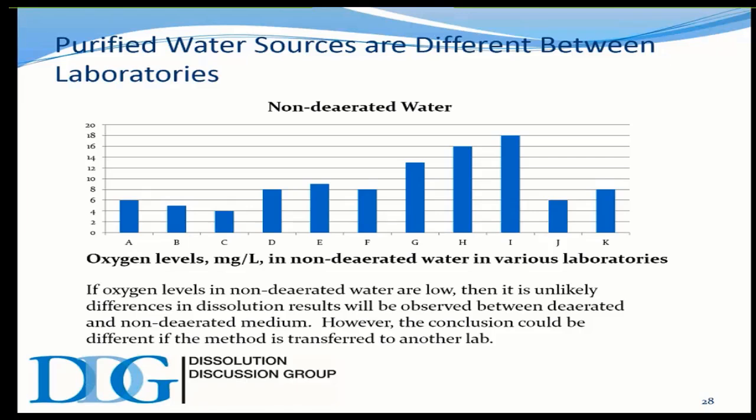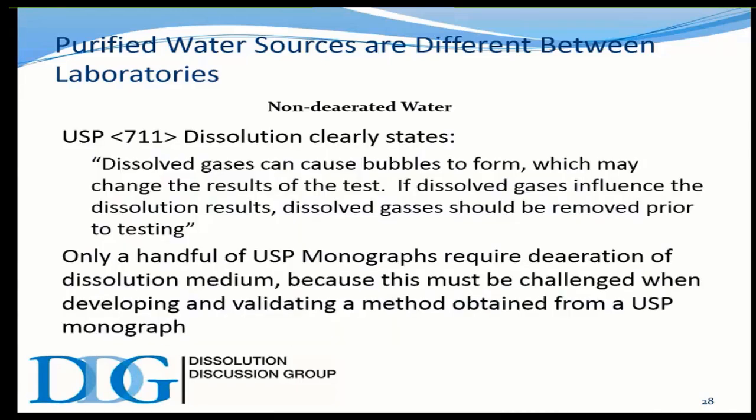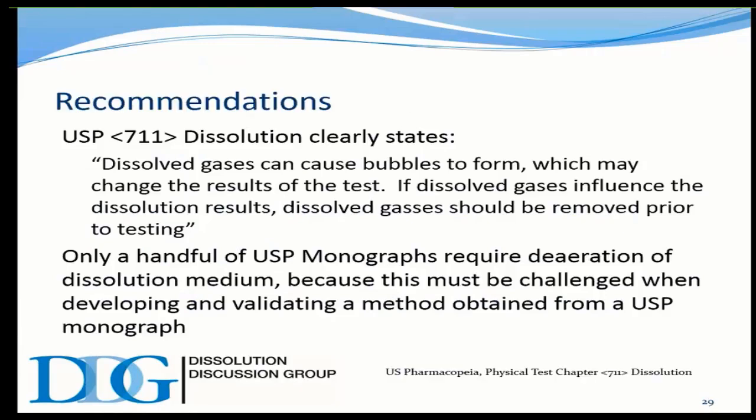Anyway, the key thing is to evaluate water on a saturated basis, and then once you've deaerated it sufficiently, down below generally 5 parts per million or so, that should be very minimal impact. So for anybody wanting to monitor it, again, I'm going to strongly suggest a dissolved oxygen type of measurement. And again, this goes in with a recommendation